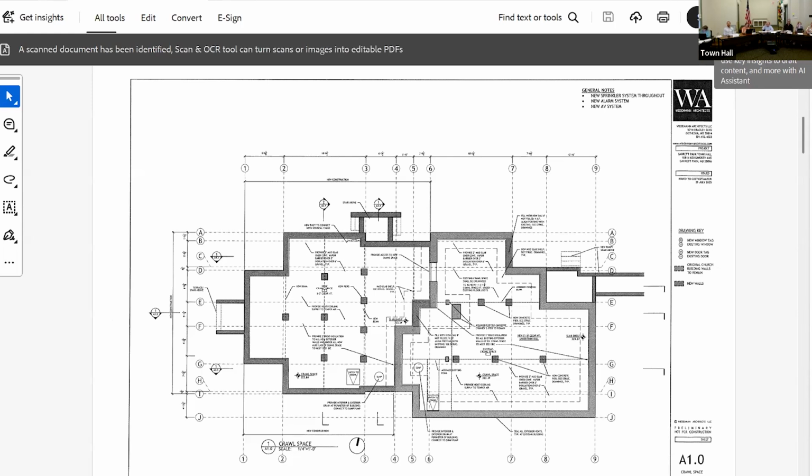And in order to avoid underpinning of the existing stone foundation, we are holding back about 2 feet. Underpinning involves supporting the walls if you're trying to lower the bearing level. Okay, next is the first floor plan.